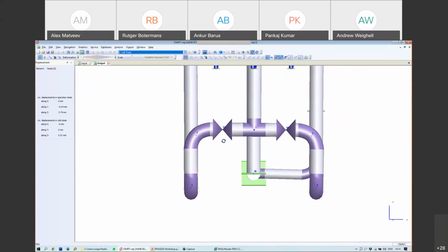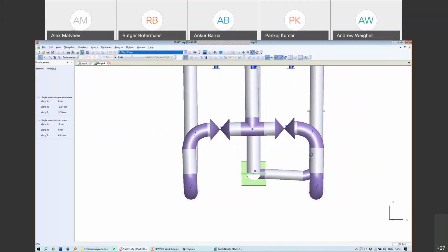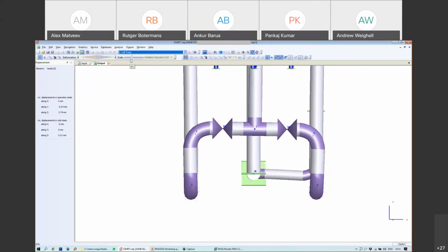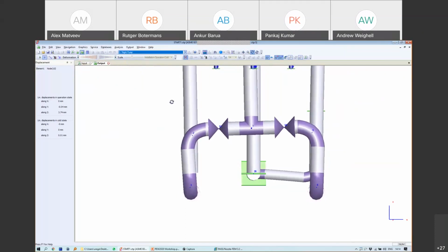As you can see, this pipe expands, but this pipe does not. So this valve is higher. And now the right pump is working. Now this leg expands. So let me show you the difference. Both legs' thermal expansions taken into account, only the left pipe and only the right pipe. So we have 3 operational modes with 3 different temperatures.